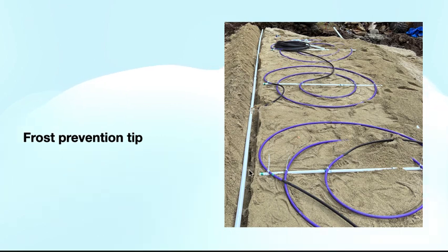It's dug down a bit, and it's not just a matter of it being dug down, but that there's a drop in an angle to allow water to drain out. The whole thought behind preventing freezing is that if the water isn't there, it can't freeze. And so we want to be able to give the water a place to go, ideally back into the tank.